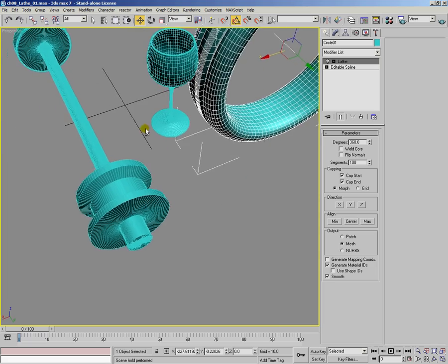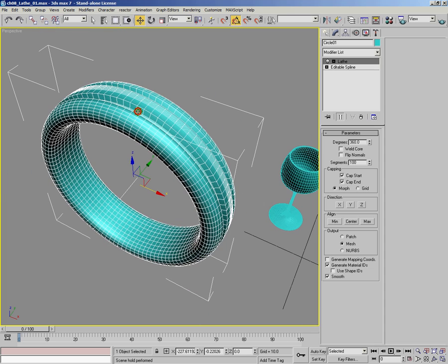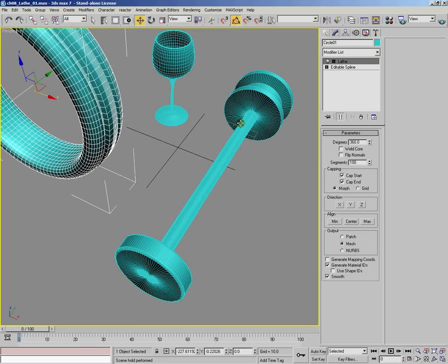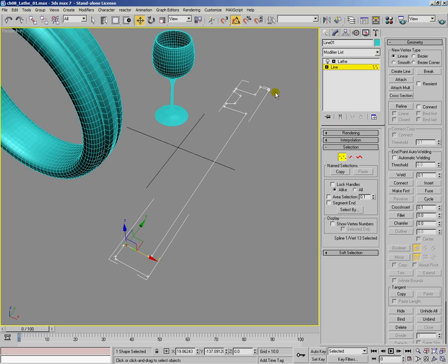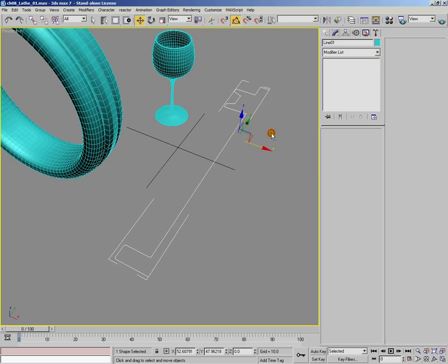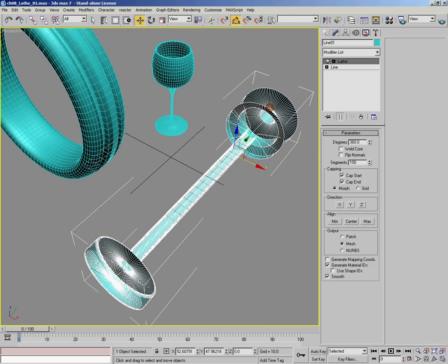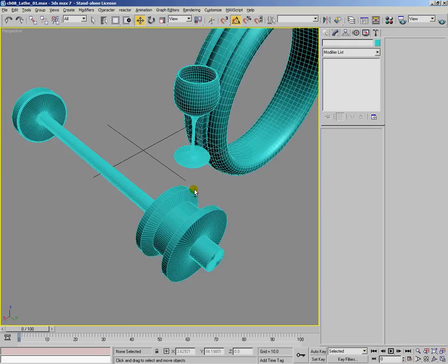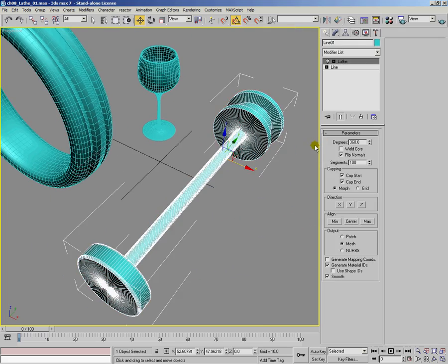If you have a surface which has the wrong direction, as we saw earlier, let's say we had this, and this is a closed spline, so it doesn't actually make much sense with this one, but this one is open. So let's say we go down here, we change it so that it's the wrong way around. So I'll just select this point here, make it the first, and now you can see it's inside out. Well, you can just use this option here, flip normals. So now you've got yourself back to where you need to be.